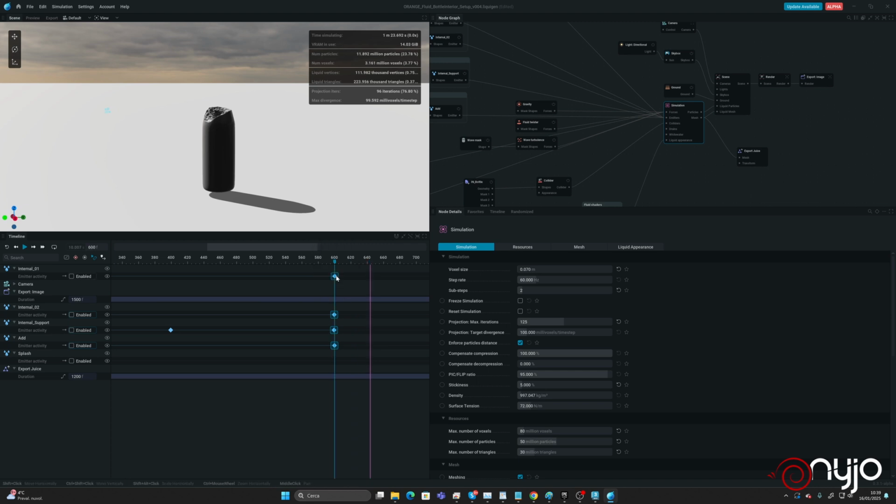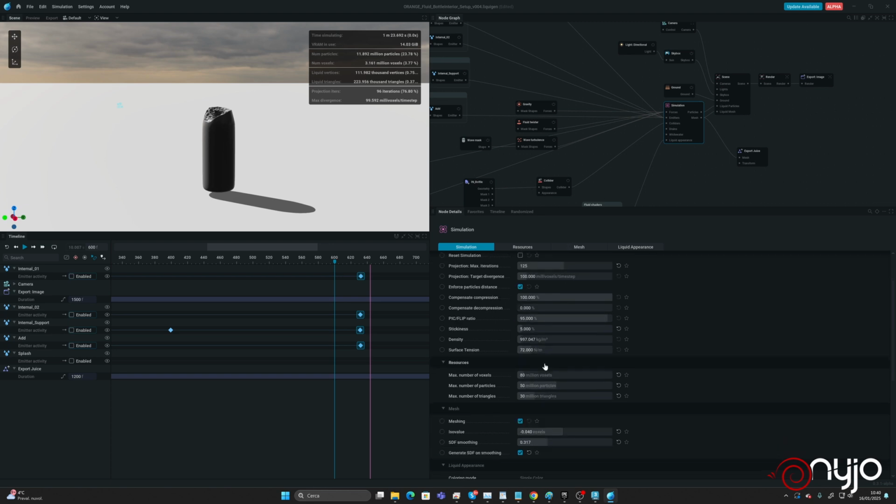So I think we can move to something like that. So we should have a little bit more fluid, and about the voxel space we can go lower and say 40, and about the particles we can go lower, and about the polygons it's the same. So we are going to use less memory.